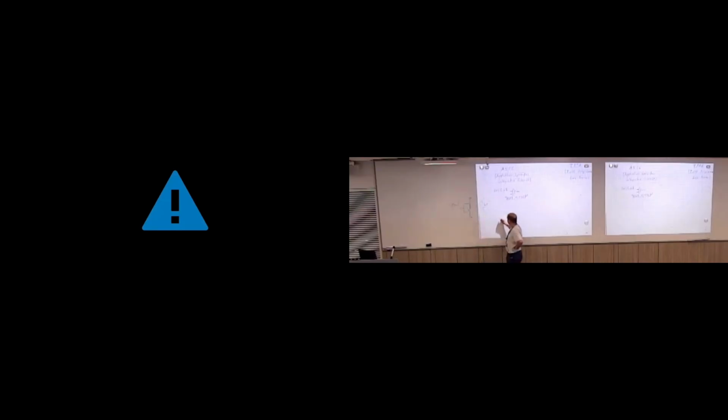So I just write the truth table. Let's say we have x1, x2, and output y. If one of the 2 inputs is 0, we want to have a 1, right? And if both of them are 1, we want to have a 0, right? Okay? That's what we want to implement. So if we want to have a 1 as soon as one of the 2 inputs becomes 0, we need for the 0 2 PMOS transistors, right?